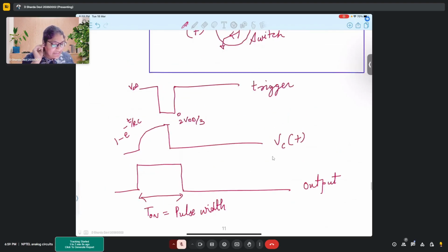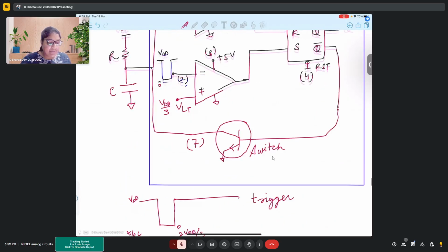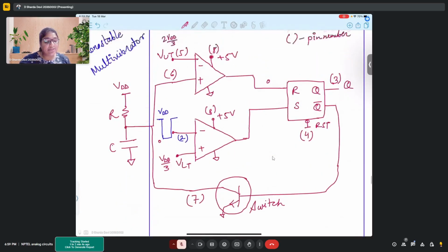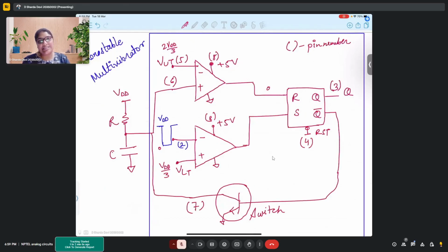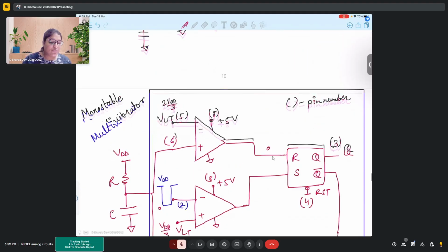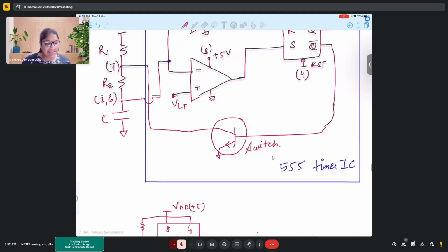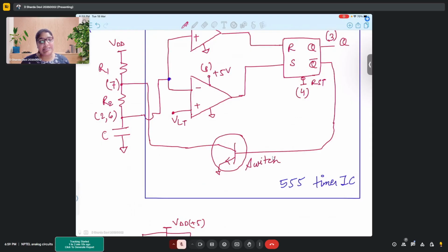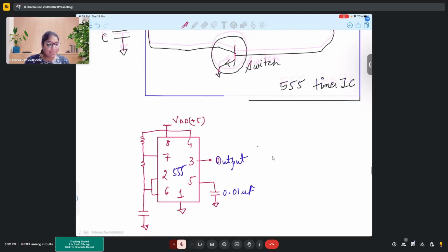And this monostable multivibrator circuit is used to generate pulses when you want certain pulses with some length. If you want square waves, continuous square waves like clocks in our digital signals, then those clocks can be generated using a relaxation oscillator or through the timer IC by using this astable multivibrator circuit.